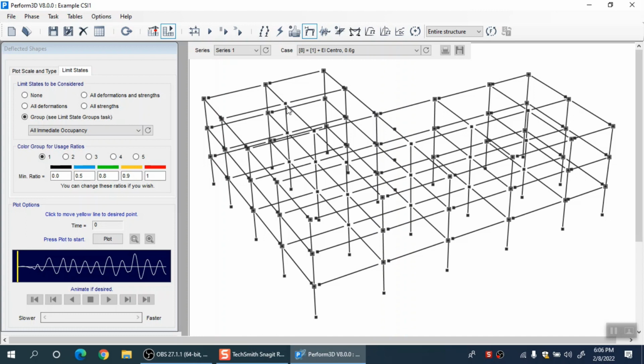But when we perform dynamic analysis, then the complete governing equation of motion, M u double dot plus C u dot plus K u is equal to p of t, will be solved, and in that M matrix only those degrees of freedom are considered which have lumped mass. So all the degrees of freedom will not be considered. Which means that for gravity load you should think of this load as some forces which are applied and not some masses which are applied, right.